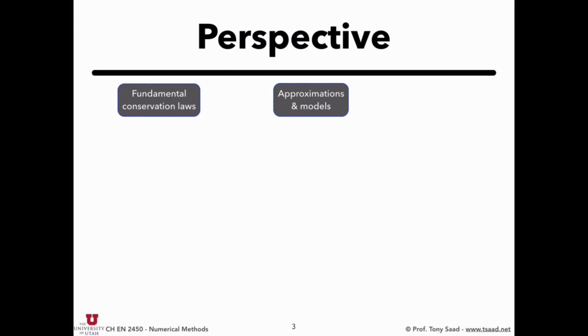Well, even more fundamentally, it's because of conservation of mass. So there's a certain mass coming out from this opening. Now, as you close the opening, that same mass needs to still come out per second. So since you've decreased the opening, to have that same mass come out, it needs to come out faster. And that's an example of a fundamental conservation law.